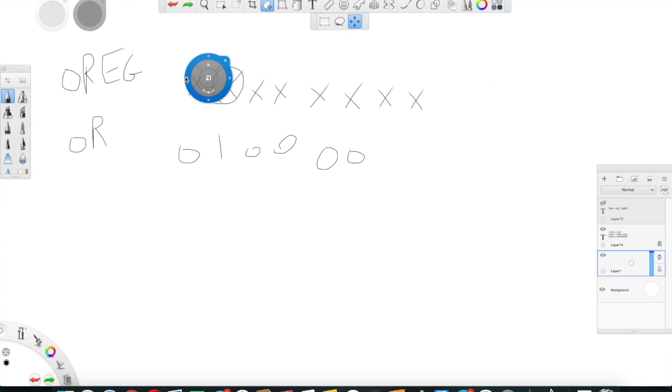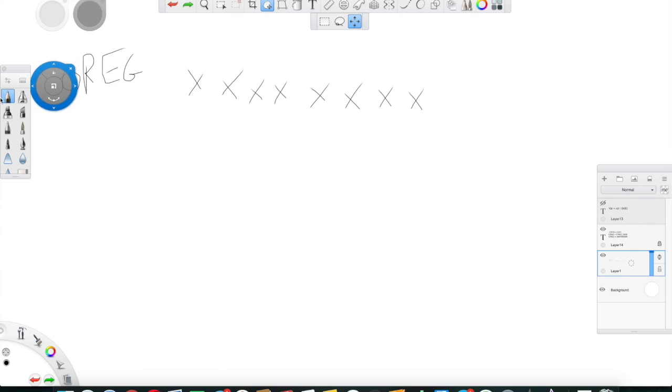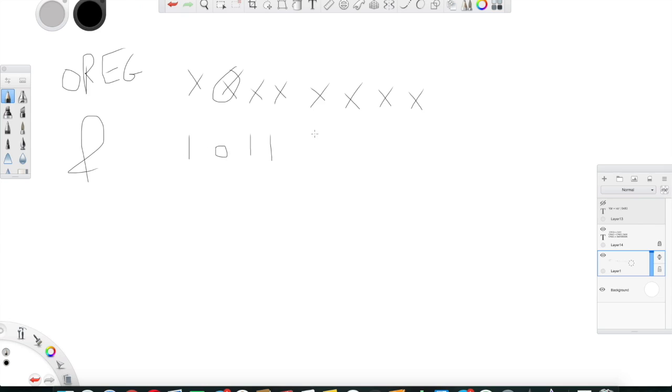So instead of using an OR, I need to actually AND, and I'm interested in bit 6. So everything I will AND with 1 here, and 0, and 1, and 1, and then 1, 1, 1, and 1. Okay, so anything ANDed with 1 will result in itself. Anything ANDed with 0 will be clear, it will be 0, and the rest will be X's. Okay, so I actually cleared bit number 6, meaning I turned the LED off.